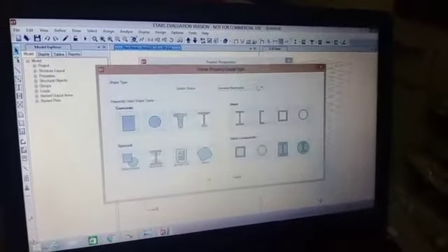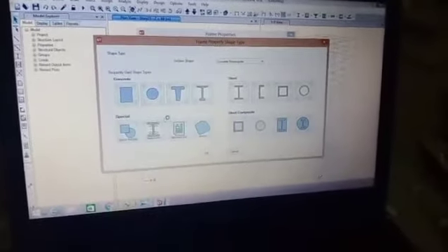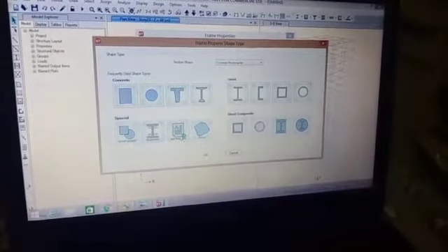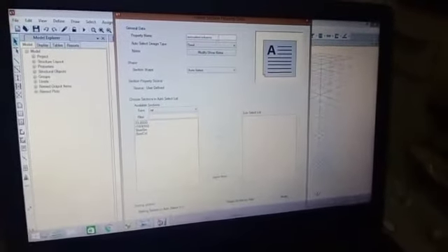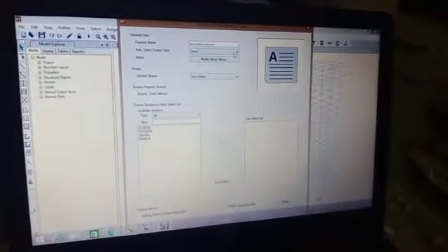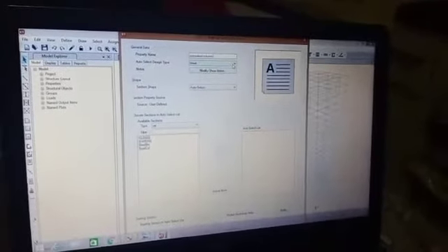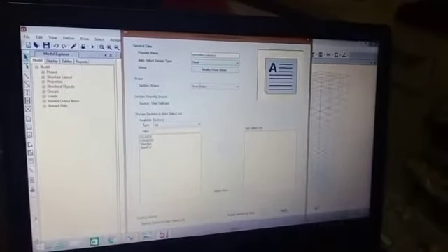Now choose add new property, and this time choose auto select, and choose the property name as auto select columns. This property is used for creating the required columns for the similar stories of the building, and auto select design type as concrete.